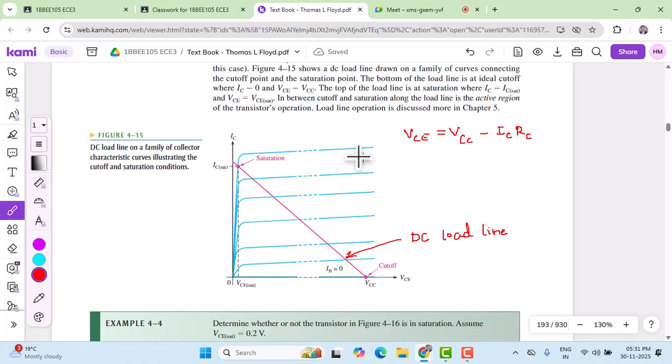When both VCE and IC are given, it should not exceed this region, so the curve here follows the PD max equation, which is equation 3. And when IC is maximum, VCE should not exceed points A and B. It should be within this range. If it crosses that, then it becomes unsafe for the BJT to operate.